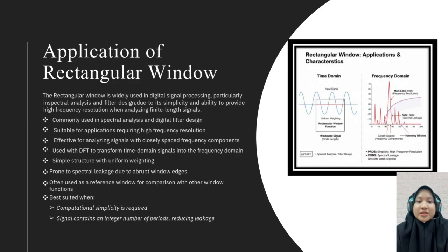Now I will discuss the application of the rectangular window. The rectangular window is widely used in digital signal processing, especially in spectral analysis and digital filter design. This is mainly due to its simple structure and its ability to provide high frequency resolution when analyzing finite length signals.